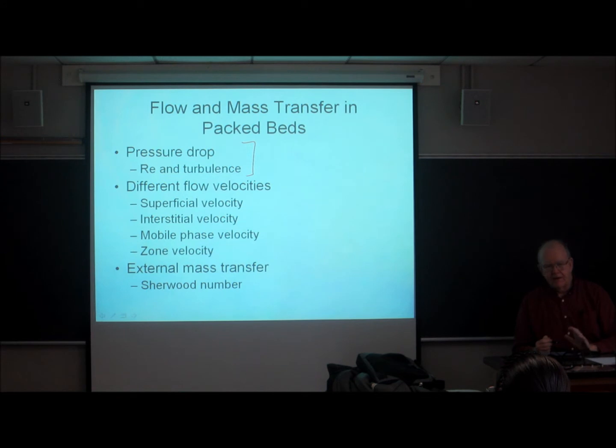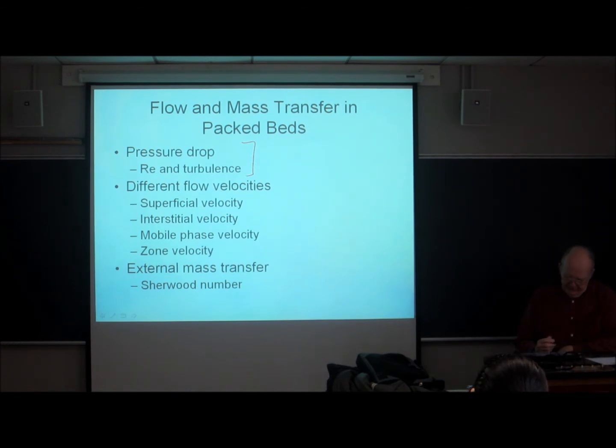And the situation in a packed bed is really very different than in an open tube. It's a good bit easier, that sounds like it's good, but it's actually bad. It's a good bit easier to get into turbulent flow in a packed bed than it is in an open tube. That's not necessarily good, because it means that you're going to have to use more pressure to get the fluid through the column. And usually in a packed bed situation, you're struggling to overcome the pressure limitations of the column.